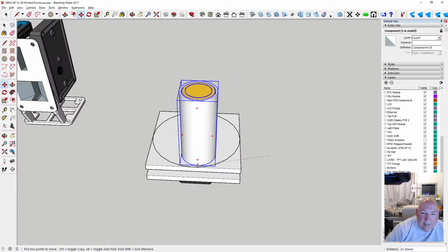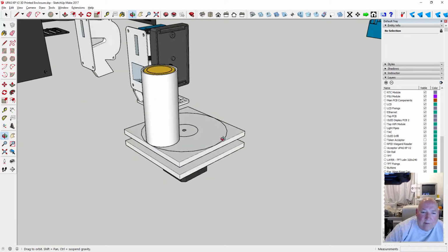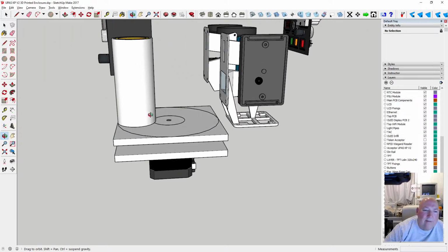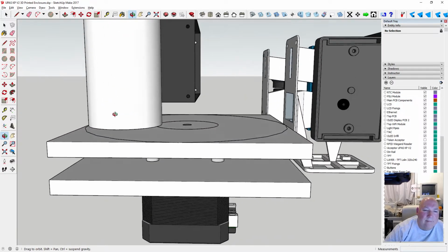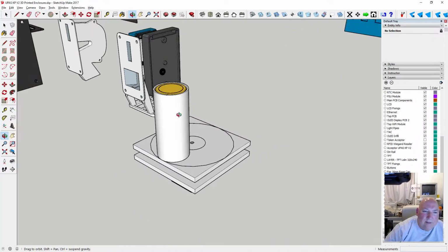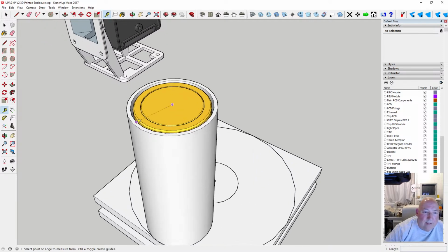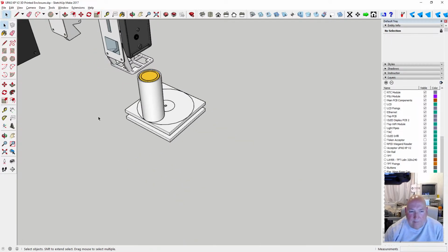So if I put it there, it should have 2mm clear. No, it hasn't. What's gone wrong there then? No, it's not 34mm, is it? It's 34mm with the clearance, but the outer bit's bigger than 34mm. 37mm. Right, let's backtrack a minute.